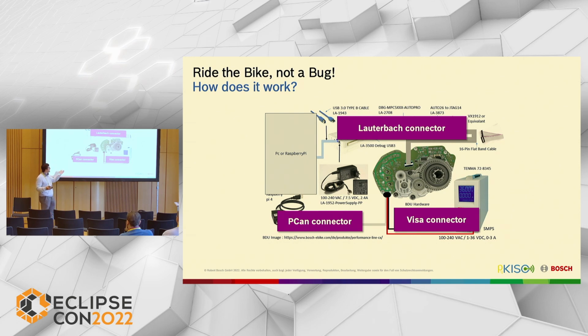Let's say now, okay, I have my 3 connectors, and I know I have access with the debugger, so maybe I could simulate or fake the speed sensors. And maybe I simulate or fake them in a way that the drive unit believes it's driving 15 kilometers per hour. I know my only interface is through CAN, because we want a higher protocol.